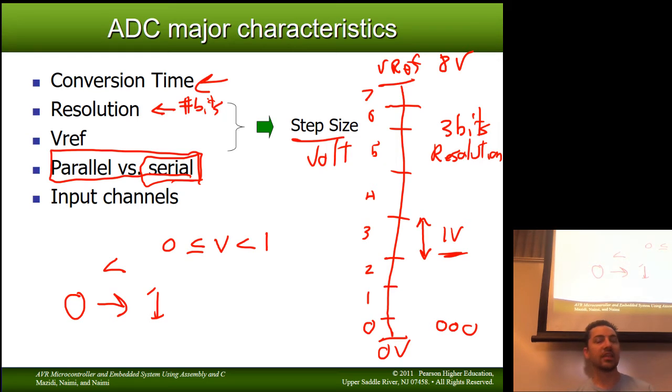One might think that that would be slower because you could only read one bit at a time, but that's not always the case. Because with parallel transmissions, it's possible to get a lot of crosstalk, so you might have to read slower for parallel. Whereas serial is only one line, you can do a lot of noise reduction, you put buffers in, it's nice and simple, and you can run it at a much higher baud rate than parallel.